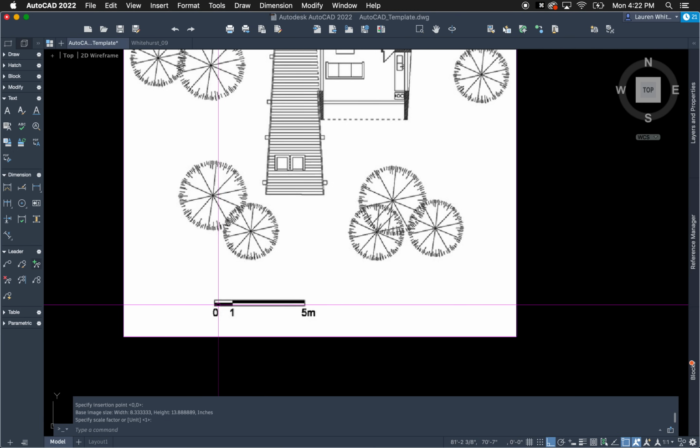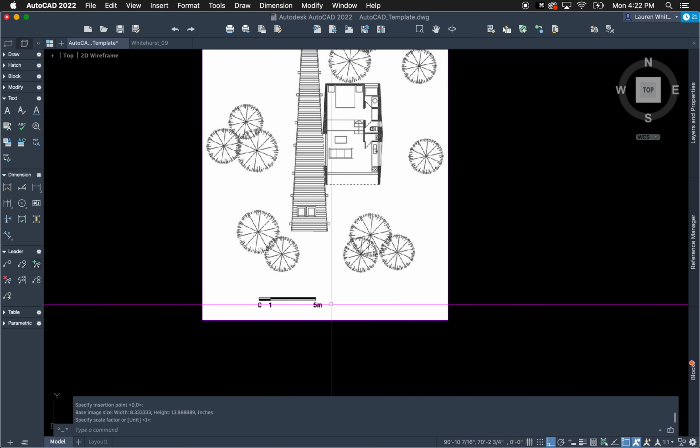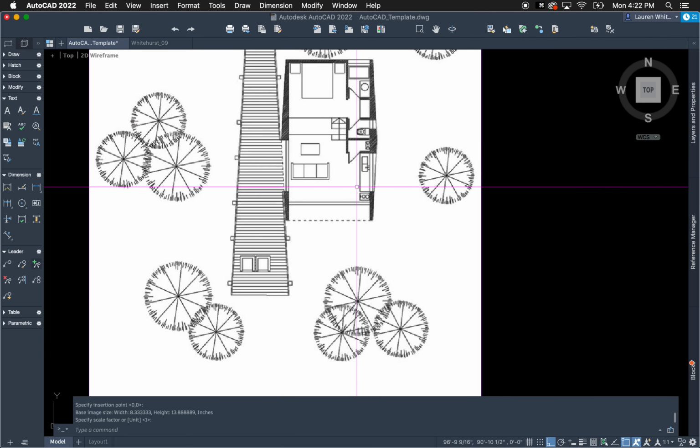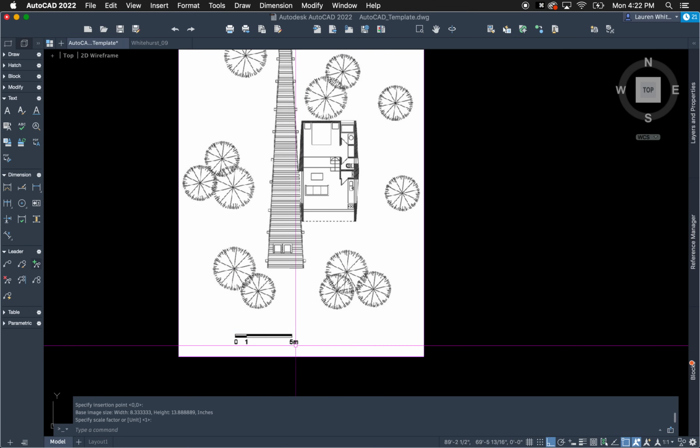And so down here, luckily this drawing actually has a scale bar. Sometimes they do, sometimes they don't. It's okay if yours doesn't. If it does, you can use it as a tool for scaling an image. If it doesn't, a helpful thing to refer to are just items in the drawing itself. A lot of times doors are somewhere between 2'4" and 3 feet wide. Counters are often 2 feet deep. So picking a dimension that's known and typical or standard can be a way of scaling a drawing if it doesn't happen to have a scale bar on it.